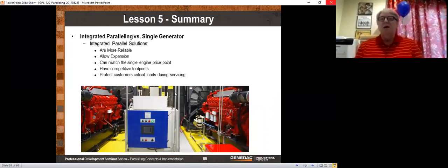avoid setting that peak. Now, if you mean that you want to actually connect those generators to the utility, can that be done? Well, it can, but now you're talking about a lot of complication. And anytime you want to connect to the utility, they're going to require an interconnect agreement and lawyers and all kinds of relays, and it gets very complicated. So I'm not saying it can't be done. And if you have really, really big generators and you want to do this all the time, that makes sense. But for the most part, it's simply too complicated and too expensive to do. And so we accomplish peak shaving by simply removing some loads from the utility and putting them on the generator in order to avoid setting that peak. And that's really easy to do.